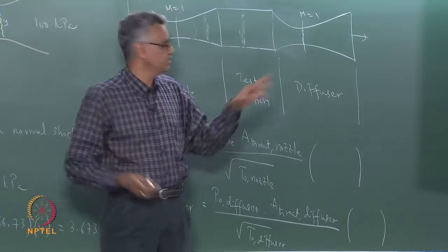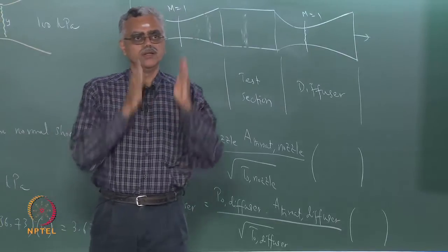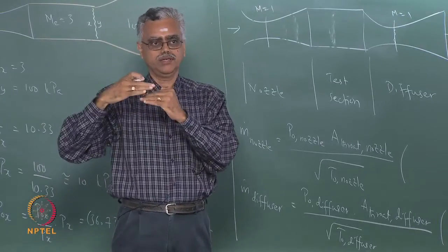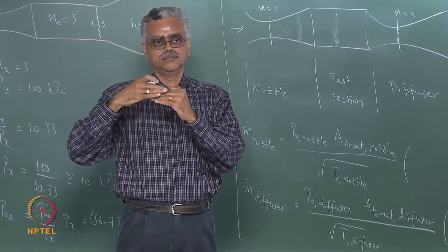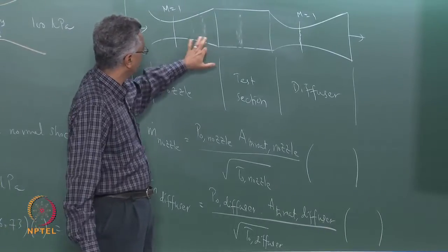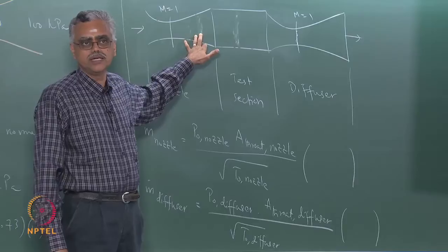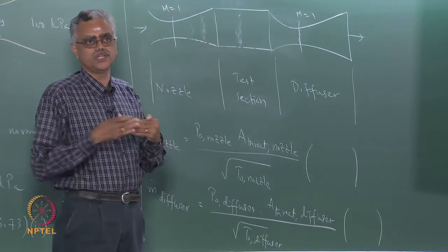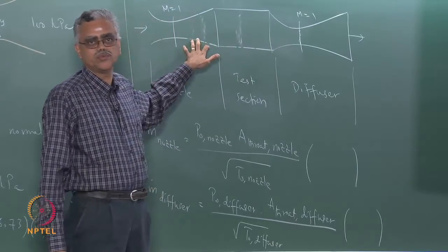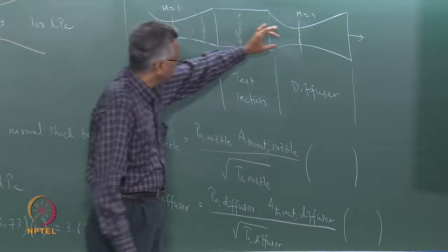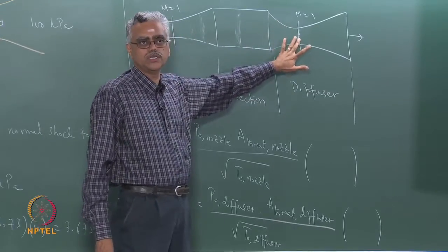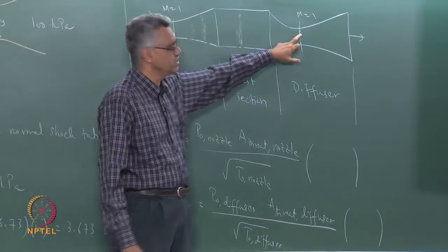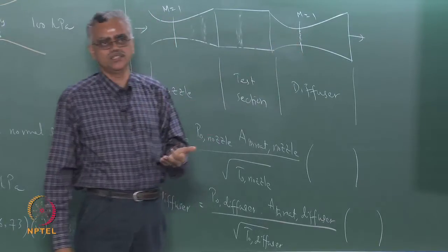For continuous shock free operation, the two have to be equal, but during startup, because of the normal shock and the loss of stagnation pressure across the normal shock, I open it to push the flow through and then I bring it back, right. That is what I do. And so, this starting shock in a supersonic nozzle poses difficulties wherever it is used. Whether it is a nozzle or a diffuser, it creates problems wherever it is used. So, we need to make sure that we understand the dynamics of what happens here, so that we can handle this properly. So, opening the diffuser to accommodate the normal shock is one strategy, but that is also mechanically very complicated to implement, right. You need to have throat areas which are movable, that is not so easy to implement in a mechanical sense in practical devices.